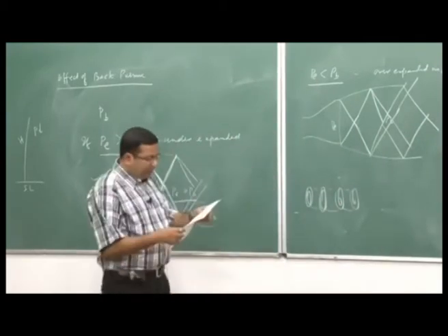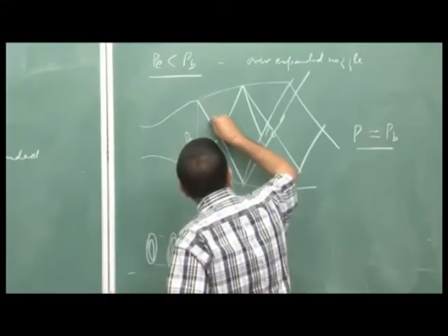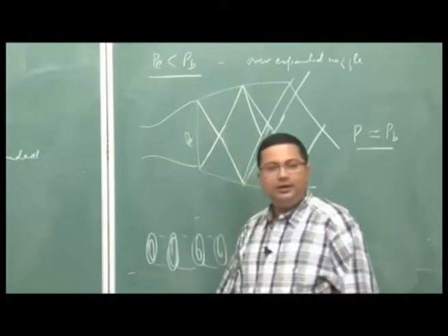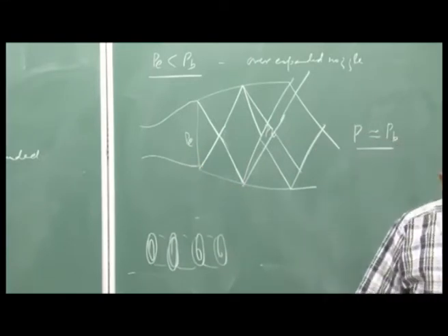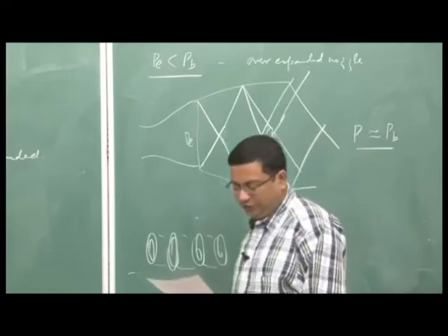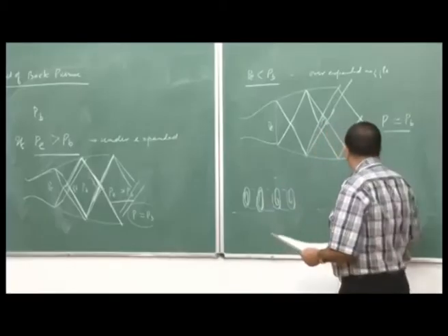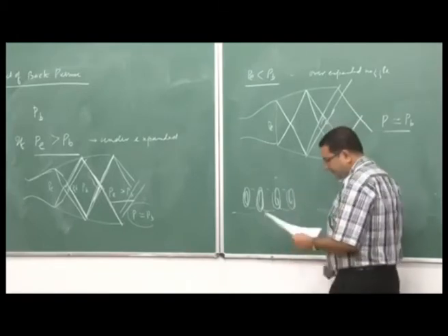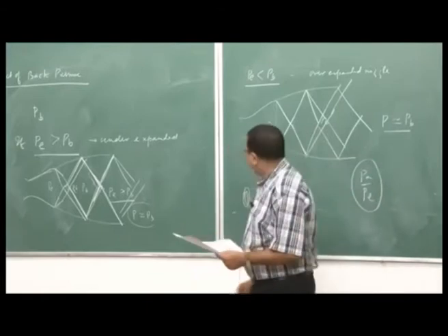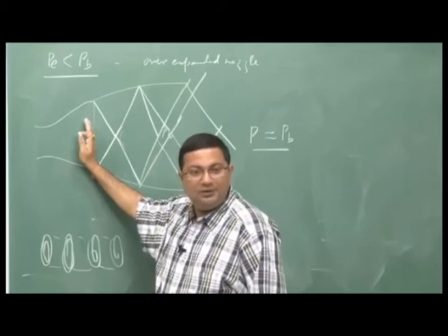So, therefore, this angle of the shock wave that is formed here is dictated by the exit Mach number Me and also the required pressure ratio. For significantly higher values of Pa by Pe, when this value is very high, then the angle may be as high as 90 degrees, that is a normal shock wave, right.